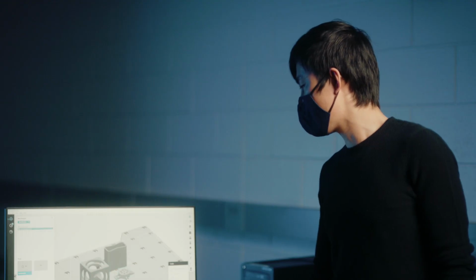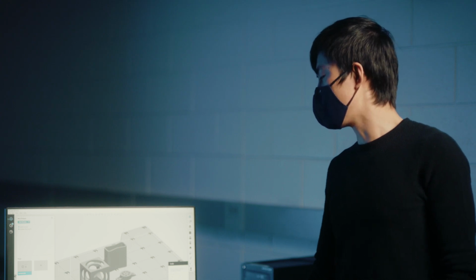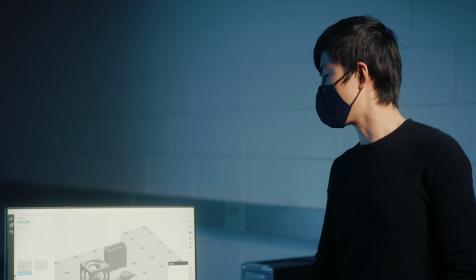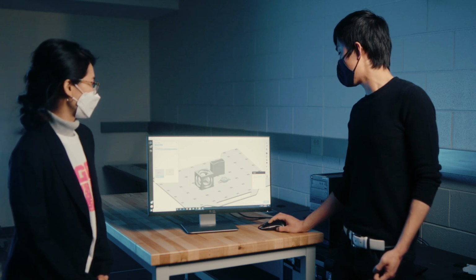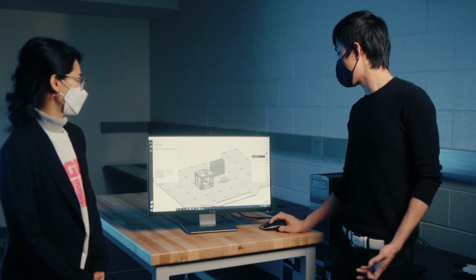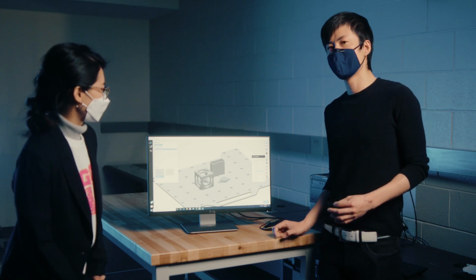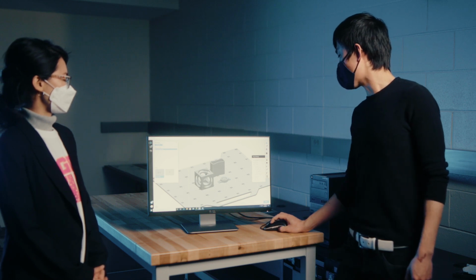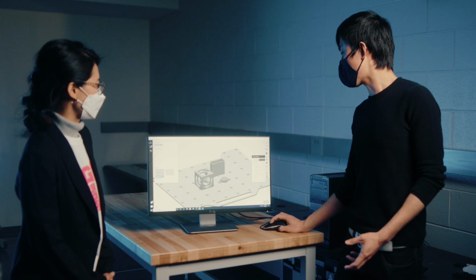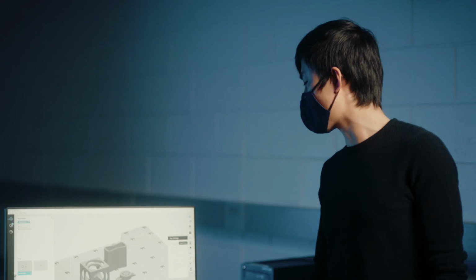And for this part, it is a little bearing. It's a functional part. So the surface finish is somewhat important, and the structure integrity is even more important. So in this case, we change the setting here. We want the tray setting to be a little bit higher, so we reduce the slice height to increase the accuracy of the model. We can change to 0.7, so that way each slice will be much thinner, which is increased accuracy.